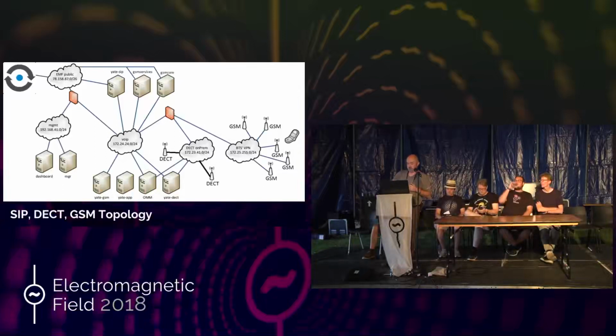We had the 2 little GSM servers at the top there. The GSM core is the Osmocom core network in a box stack. So for those of you who know the GSM acronyms, the MSC, the BSC, the HLR, and the SMSC were all running in one on that box. That just has a SIP interconnect, so that came out over SIP that way. And then the GSM services was just an Asterisk box for doing a few little hacks and tweaks, and we put a few little services on there and test numbers, and generally it just gave me a box to do some manipulation. We also routed the outbound traffic to Nexmo through that, and the inbound.